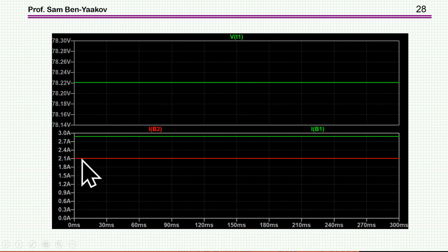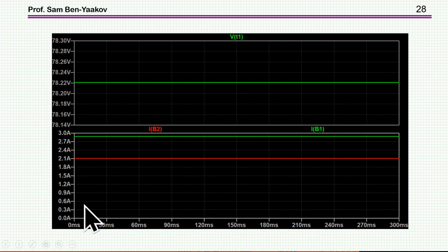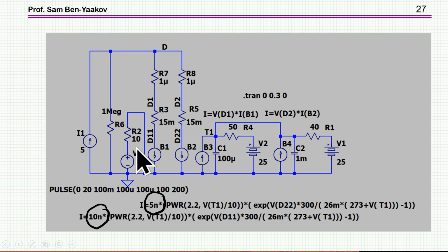The difference, however, is not as much as you'd expect, because here there is a 50% 1 to 2 ratio, while here it's not 1 to 2, it's 1 to 1.5. Well, the reason is that I'm still having here the internal dynamic resistance, which is helping a little bit in the balance. So this is why the difference is not as big as the coefficients here.